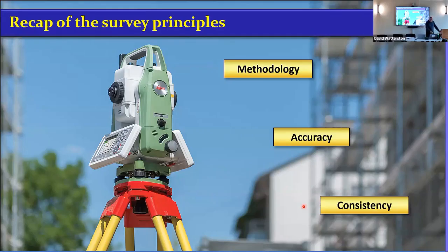And so for consistency, I had to make sure that my kit used was the same. Obviously, temperature affects everything, whether it be a steel tape or a bit of wood or an instrument. So temperature and the moisture in the air affect either the infrared signal or the laser signal. And we're not talking about a lot, we're talking about tens of millimetres or hundreds of millimetres. But anyway, in this particular job, it might have had an effect.